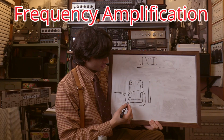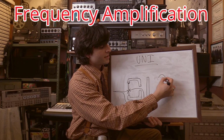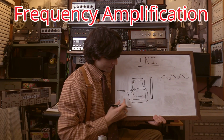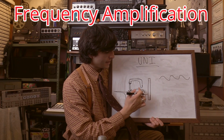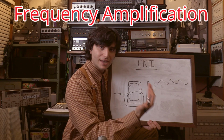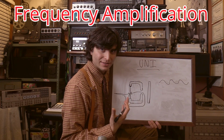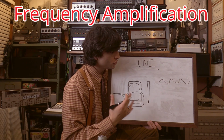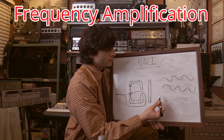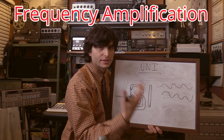So in other words, the diaphragm is going to be seeing the signal from this first path as something like this. And because of this time delay that the second path has to take, it is going to be offset a little bit in time. But the mathematics that the designers of the microphone used made it in such a way the two signals will match with one another and amplify the signal.